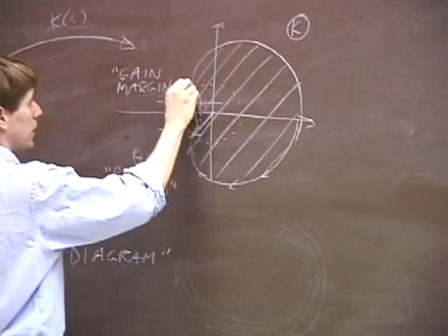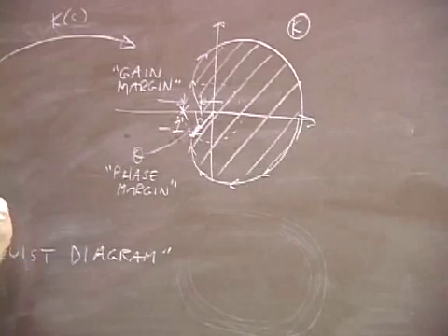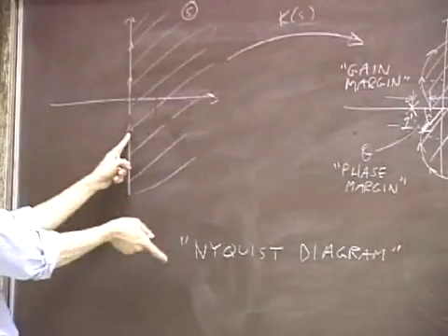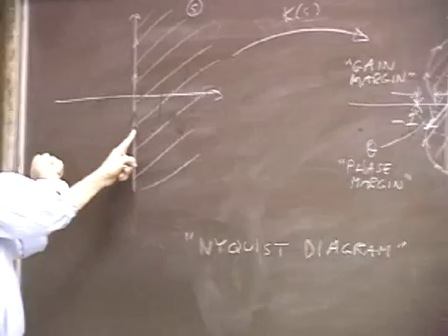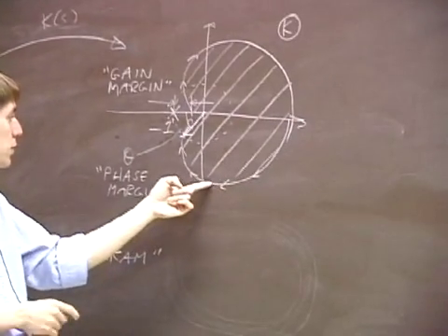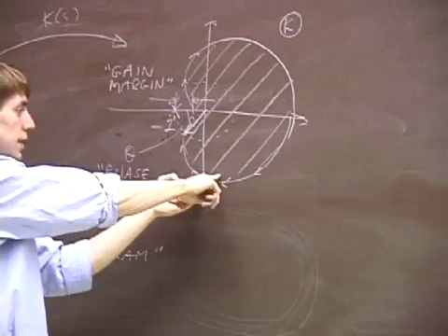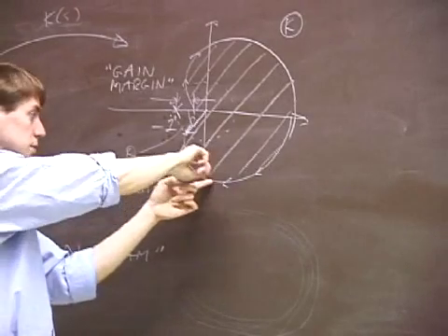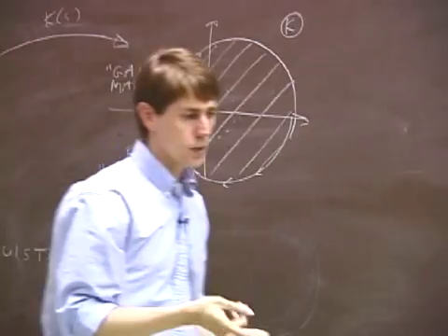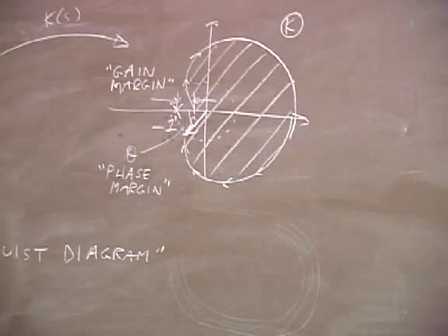And in fact the direction gets preserved. So if you're on this line and going this way, whatever's on your right is in the right half of the S-plane, whatever's on your left is on the left half of the S-plane. Same thing over here. As you travel along this boundary, whatever's on your right hand is something that got mapped from the right half S-plane. Whatever's on your left hand got mapped from something on the left half S-plane. So that's what you do. It's not nearly as computationally intensive as you might think from just looking at the region.